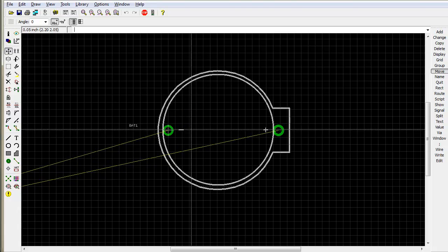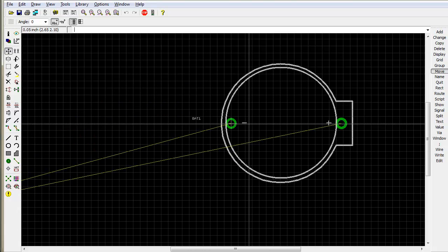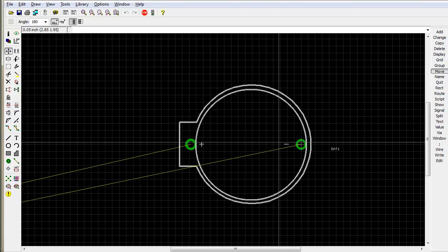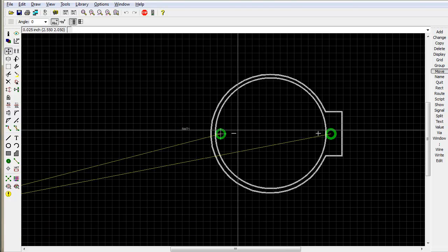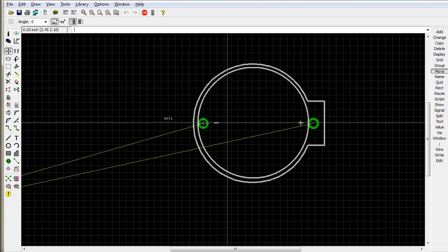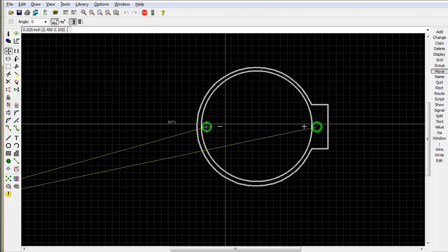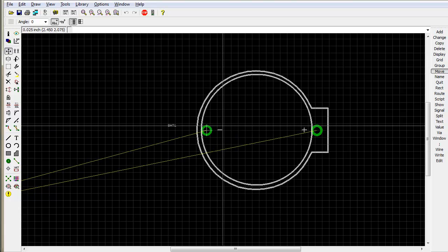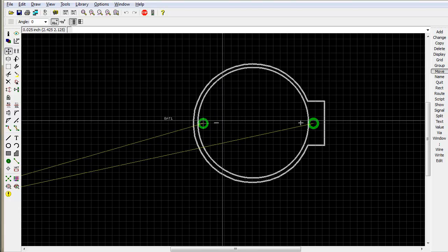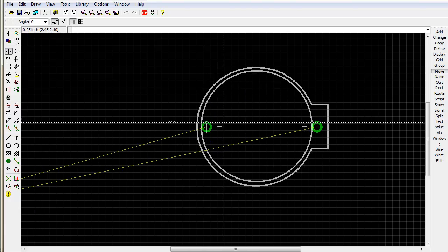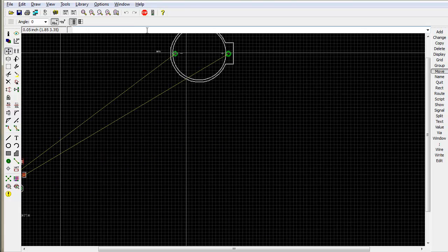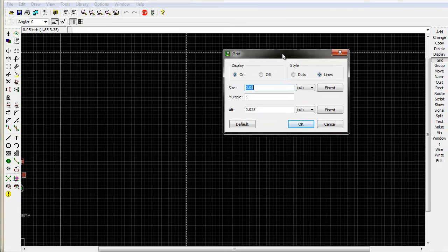The crosshair here is, if I rotate the part, you'll see the crosshair on the left is where the grid will go to. If I press the Alt key and bring it around again, it'll move a fraction of the grid. So it's basically 0.5, and then the normal size, and then 0.025, which is half that step. Okay, so yeah.